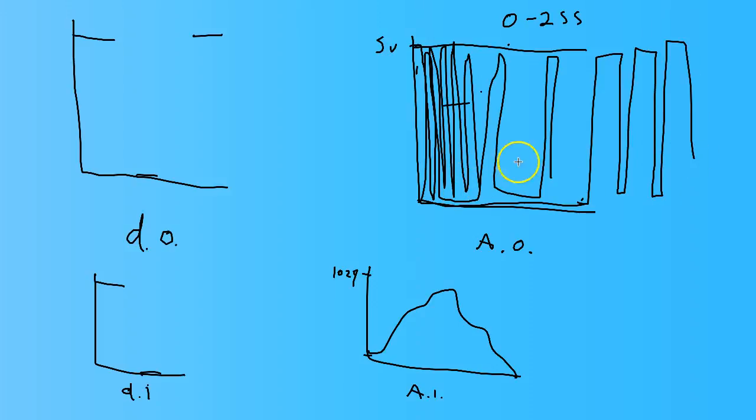Okay, and so if you use this to control an LED, if you have a value close to 0 like this, where it's turned on for short and then off for a little bit, then this is going to look really dim. And if you have something close to like this, it'll look brighter. Okay, and so this is when you use the function AnalogWrite, which is what I'm going to introduce now. So you can control brightness of LEDs, but it's technically not analog because it can only be 0 or 5 volts. It's not some value in between like we could do with the analog inputs. Okay, so let's go ahead and give this a try.